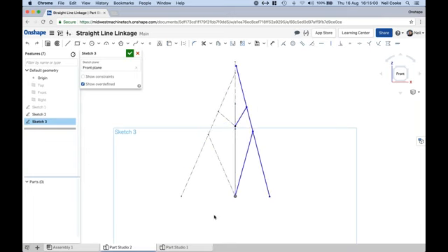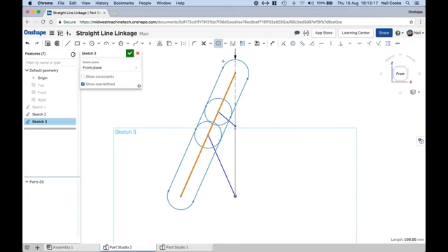And we can still get the very same motion. Now to build your 3D model from that is just a matter of selecting the geometry and building other sketches around them. So for example, you could pick these 3 guys.